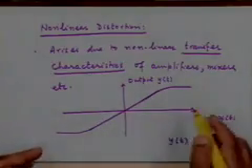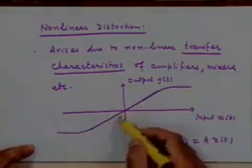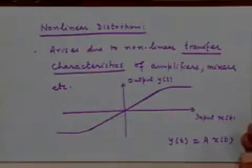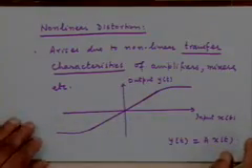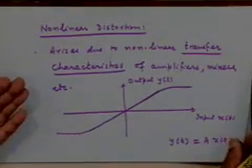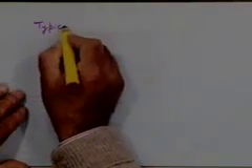You have to introduce, can you suggest some model for this curve that you have here, some suitable parametric model? For example, we can possibly model it as a polynomial of some kind. We can find suitable coefficients of a polynomial such that the resulting curve would look like these characteristics, and that's a usual thing that is done to model nonlinear components, nonlinear devices. Use polynomial models.